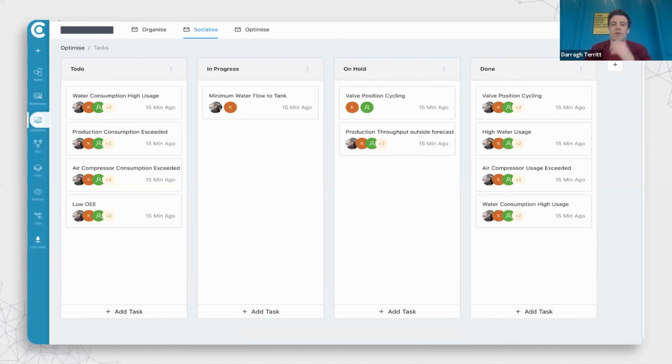So for years, the site had not been bypassing that chilled glycol circuit away from the hex during the process, which happened a couple of times a day and led to chillers being under tremendous pressure to bring down the temperatures of that circuit. So that simple oversight led to around 25,000 of wasted energy a year, all because the data from the two systems were separated and were not being analyzed in the same location together.